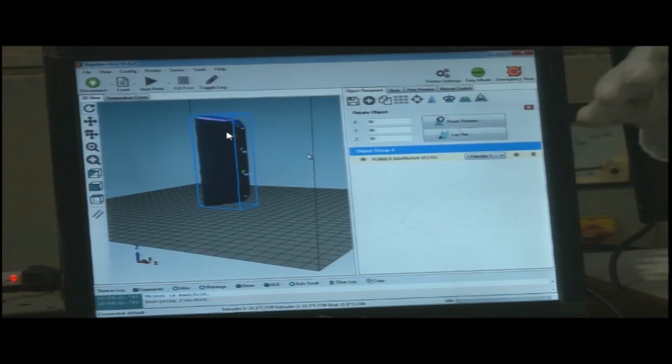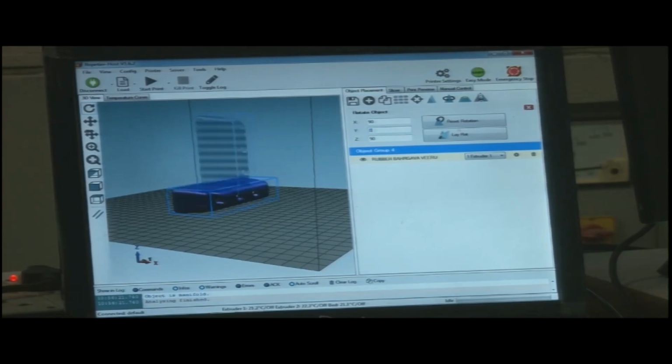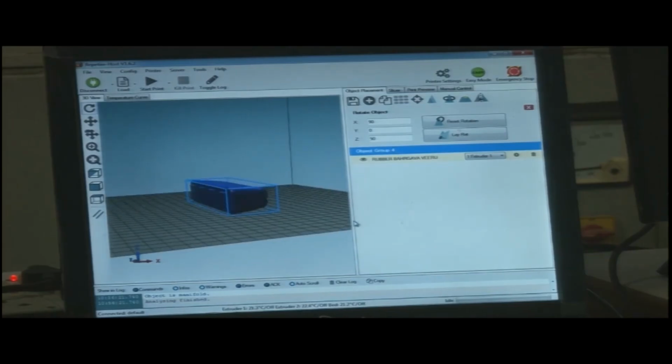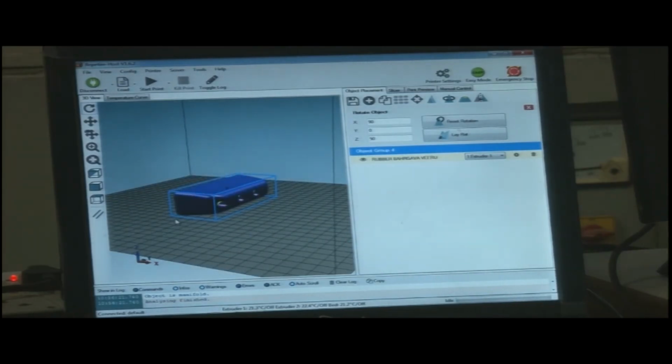Total time means total economy, so the total cost of the product would also increase, because in the product cost function the machining time is one of its factors. So this is not a very good position to manufacture. So we can opt to select a flat position and orient the job in the proper place and position.